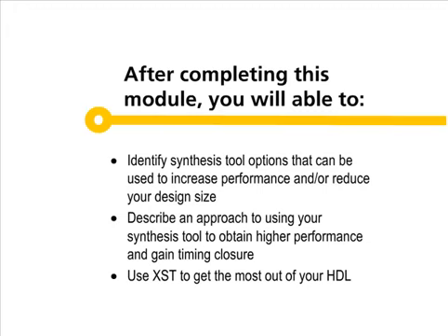The guidelines in this module are not specific to any particular synthesis tool or Xilinx FPGA family. However, at the end of this module, I will discuss the XST synthesis options and show you how to find them. The options we're going to discuss will provide support for all of Xilinx's FPGAs.